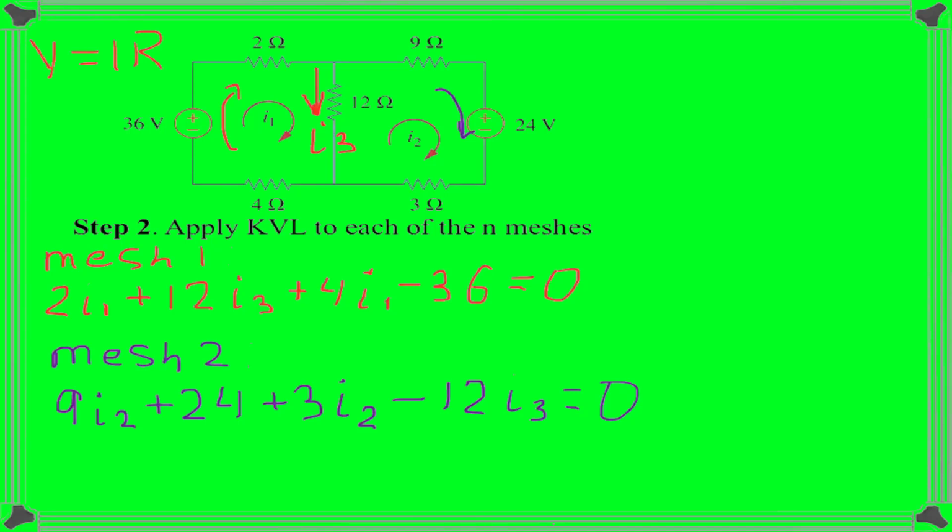But now the interesting question. First of all, we just wrote 2 equations, but if you look on this, we have more than 2 unknowns. We don't know what is mesh current I1, we don't know mesh current I2, and we also don't know the mesh current I3. So what do we need to do? We need to substitute mesh current I3 by expressing it via I1 and I2.